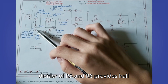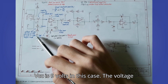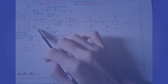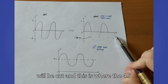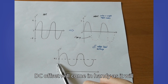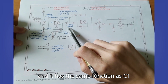The voltage divider of R5 and R6 provides half of the supply voltage, allowing it to work in single supply mode. Since VCC is 9 volts in this case, the voltage divider will provide 4.5 volts. This is important since the op-amp is working in single supply mode. This means that the negative sides of the waveform will be cut, and this is where the 4.5 DC offset will come in handy, as it will shift the entire waveform upwards, making sure no part of the waveform is cut. C4 is located at the output of the op-amp, and it has the same function as C1.